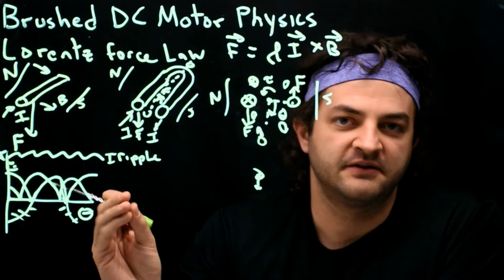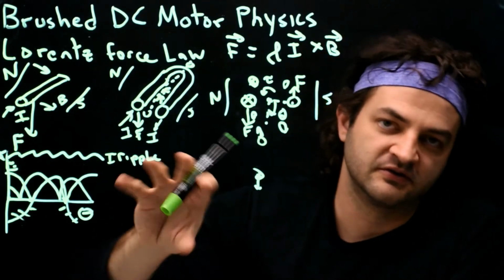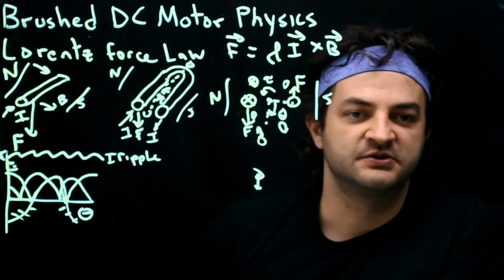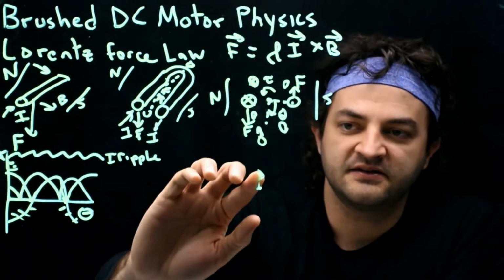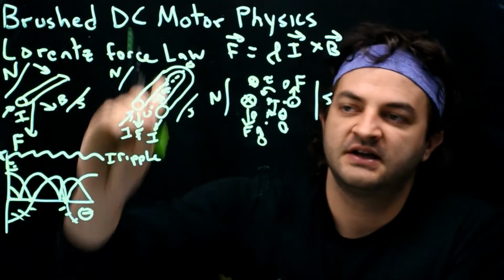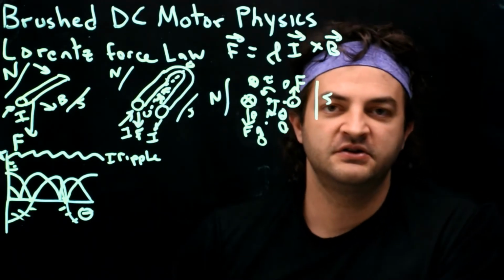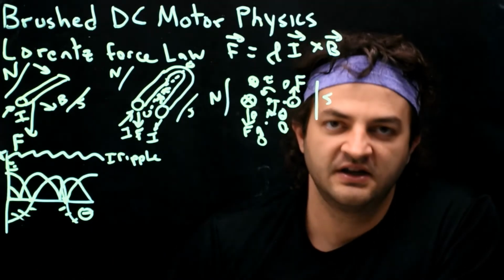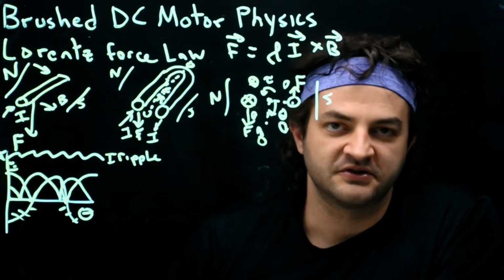A stepper motor, you kind of do that blindly, where you assume that the rotor is in a certain position and you just turn the coils on and off. A brushed motor, which is an older type of motor, does it mechanically. It mechanically commutates which coils get the current, so that you don't need any smarts. So this was kind of invented before microcontrollers or even digital logic. So it made it a lot easier to control these motors.